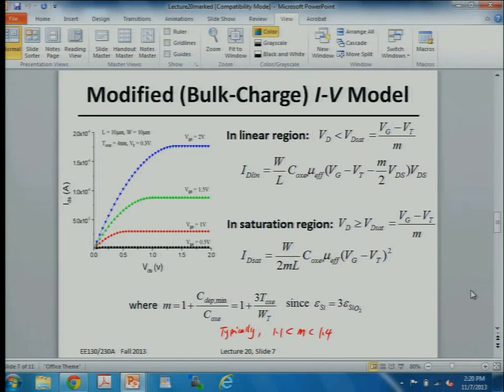same thing, except now the maximum voltage you can apply, which determines the electric field and therefore the drift velocity, is going to be limited to VD sat. So no matter what the drain voltage is, the voltage drop across the inversion layer is just equal to VD sat. Any extra voltage above that is dropped across this pinch-off region. Okay?